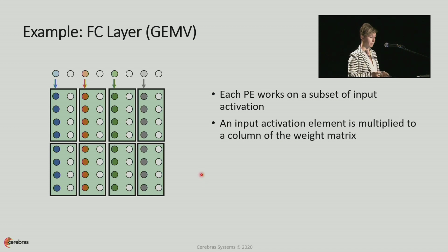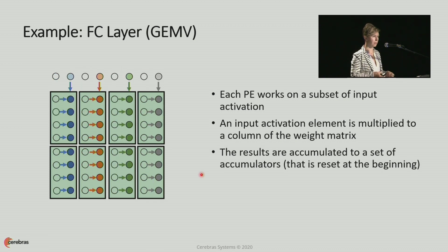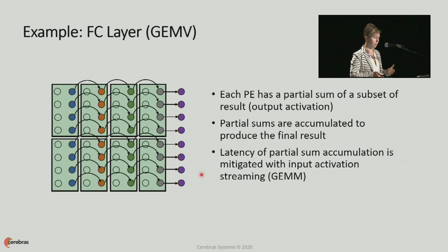We start by multiplying all the weights which are local to this PE by the input, and then we proceed with our add accumulates. At the end, every tile will contain a partial sum of part of the output. Then we accumulate all of those partial sums and produce the output, with different parts of the outputs produced by different tiles.